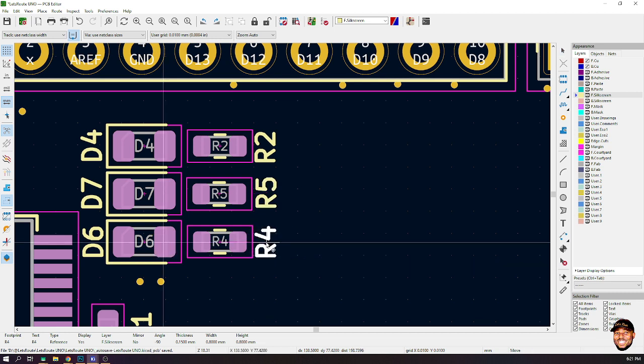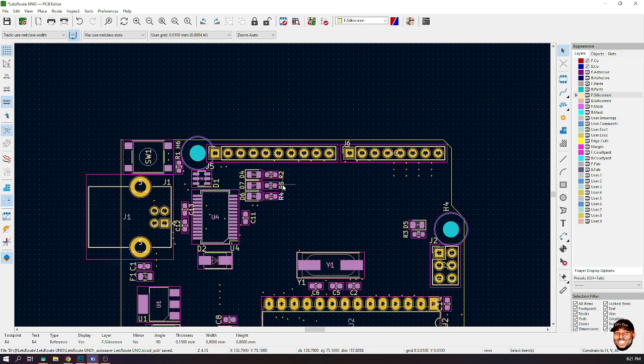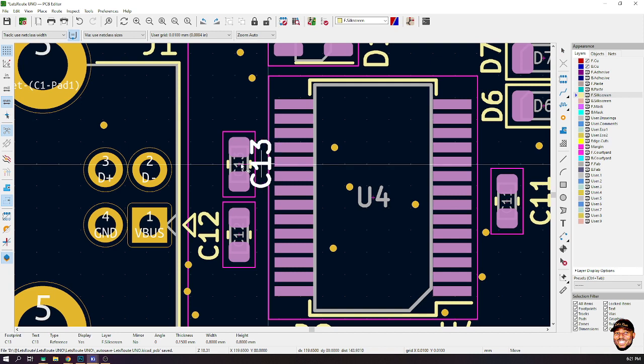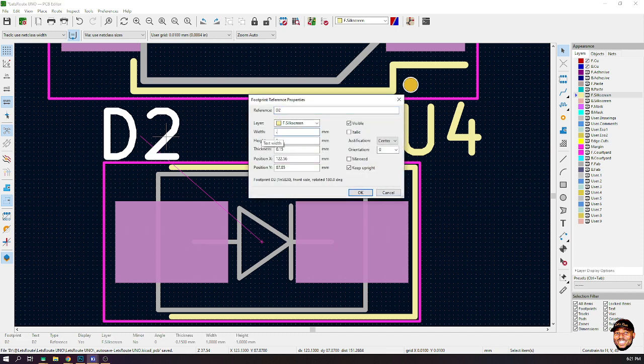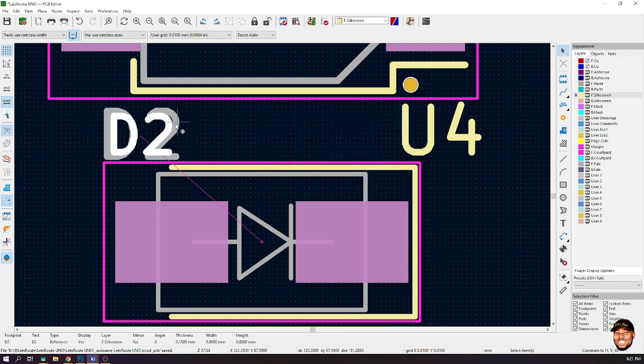Now, when you are placing silk references or you are designing your silk screen, make sure your silk screen avoids this line, else they will be cutting through. And always please find time to pay attention to your silk screen like you pay attention to your tracks. Make it a habit so that it will always be easier for you. I am always very peculiar and interested in the outlook and the way the board looks. So I really don't joke with my silk screens.